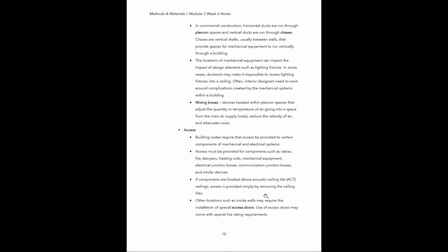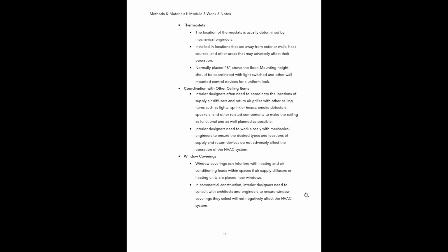Okay, so you're basically introducing a vulnerability into the fire protection system, and you have to then basically undo what you did by using a special sealant around the outside of the door. There's all kinds of things required by code that you're going to have to incorporate to get that fire rating back up to where it was prior to adding in the penetration. All right,